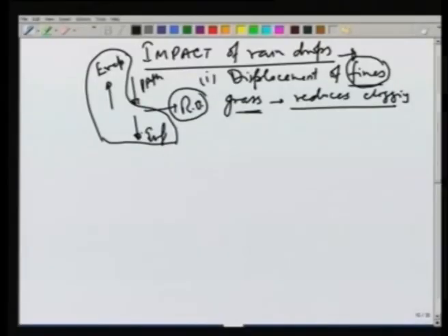From surface water resources point of view, evaporation and infiltration would be abstractions. If we talk about groundwater sources, then runoff would also be an abstraction, but infiltration will not be. Transpiration will be an abstraction. For an irrigation engineering point of view, evaporation and runoff both can be thought of abstraction, and the deep percolation towards the groundwater will also be an abstraction.